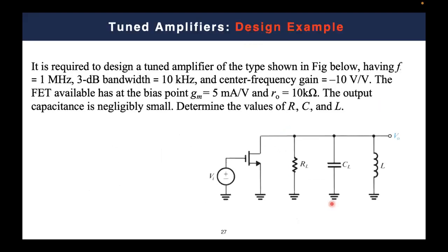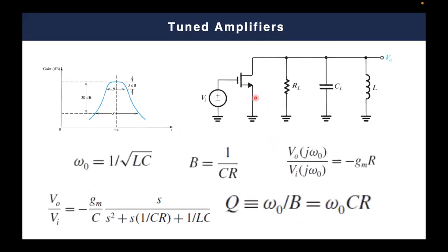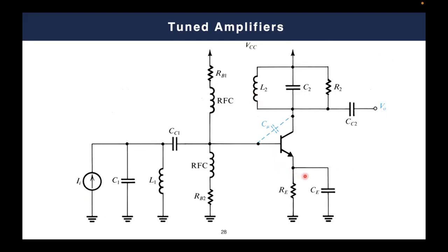So if you remember this here, you will find this is a short circuit, but typically it's not a short circuit. It has a resistance value, but this resistance value will not be shown during the AC analysis, because the capacitor will act as a short circuit, as I just mentioned, and it will reject the effect of the resistance during the AC analysis.